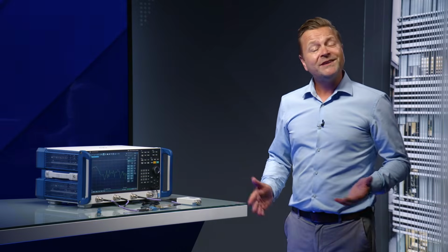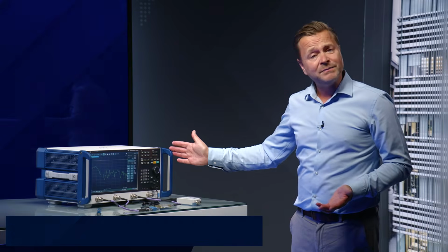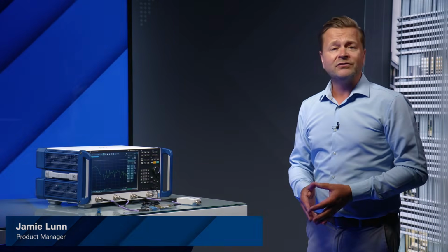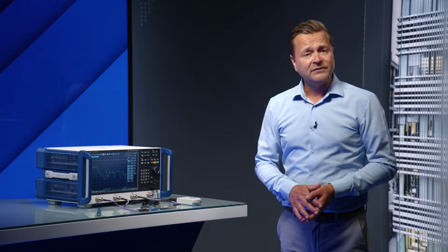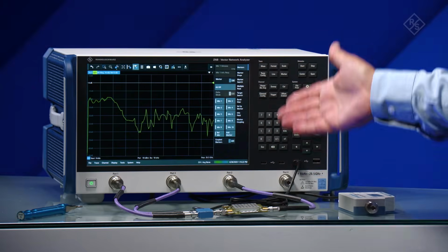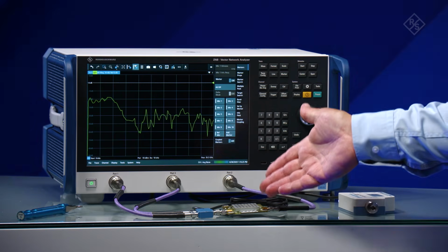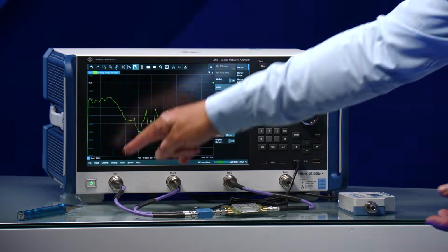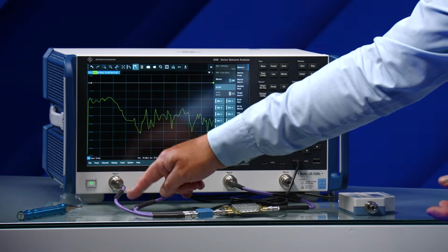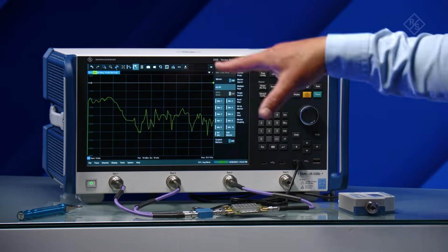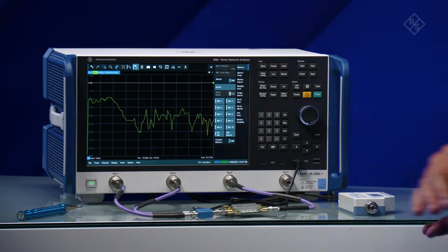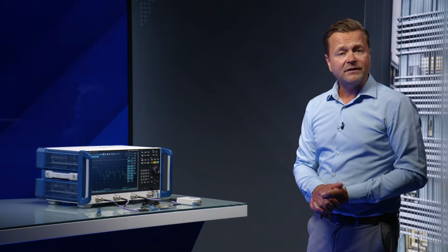Hello and welcome. Today I'd like to show you how we can use our ZNB3000 network analyzer to perform two-tone intermodulation measurements on an active device. Here we have a small signal USB powered amplifier, which we'll use as part of the demonstration. And we're feeding the two tones that are coming from port 1 and port 3, which have separate signal generators behind, in through an external combiner to provide the two-tone stimulus into the amplifier.